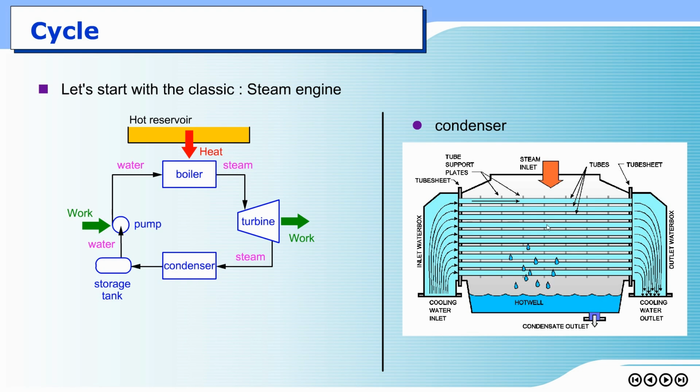Along the way, the temperature would be reduced by cooling, by the heat transfer out of the steam into the cooling water. If I continuously supply this cooling water, we can imagine that its temperature remains constant, and we call this cooling water the cold reservoir. So we can draw the cold reservoir here, and there will be heat transfer from the steam inside the condenser in this white area into the cold reservoir, so that all the steam will be condensed into liquid water.